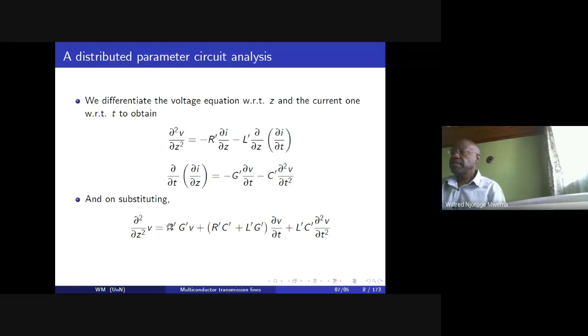And we note that on this other side, we just have a voltage differentiation with respect to distance. Therefore this is a resistance per unit length, and that is a conductance per unit length, and so we see that this product is going to be per meter squared, or per distance squared, okay? And it will have no other dimension. We can see that this side will be V over area, and that will be V over area. So at least for the first time we are okay.